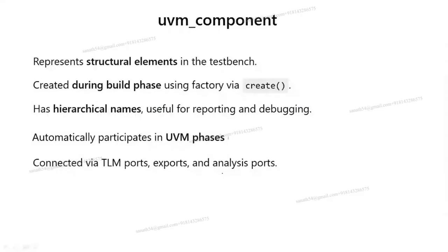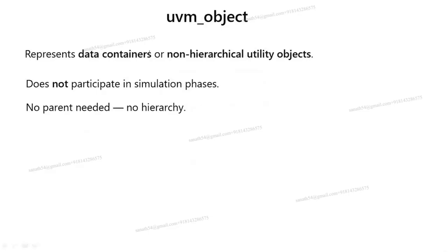UVM components are created via a constructor called create, which we'll discuss. Those are connected with the TLM ports. And UVM objects are data containers or non-hierarchical utility objects. These will not participate in simulation phases.